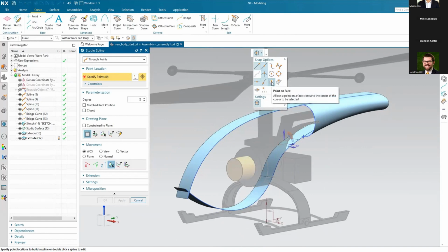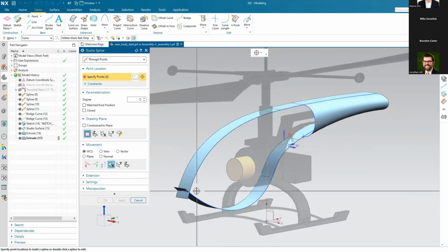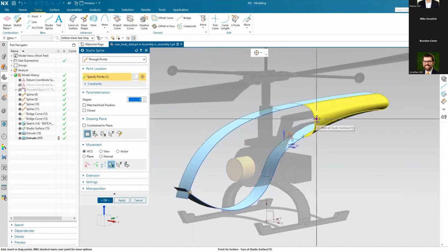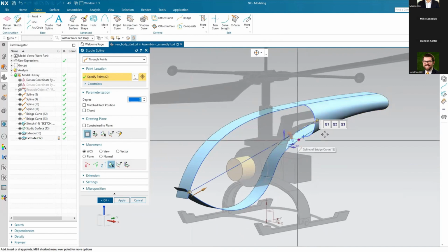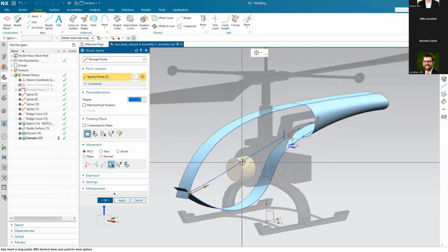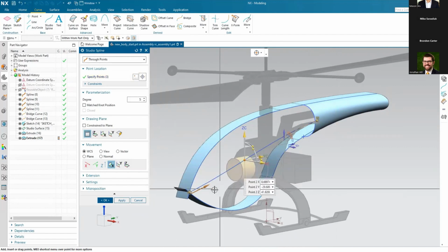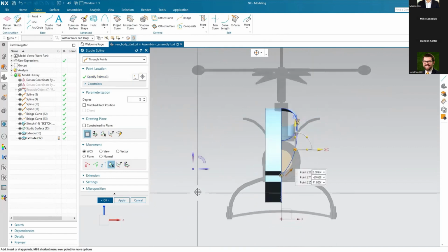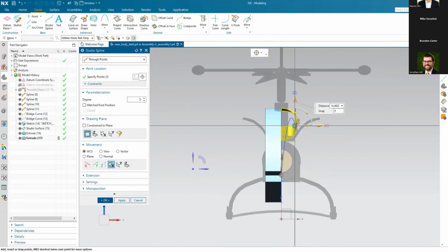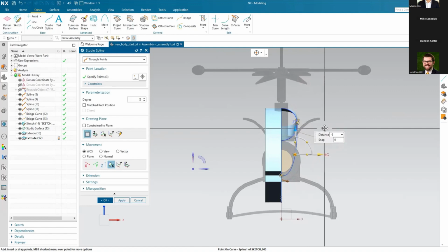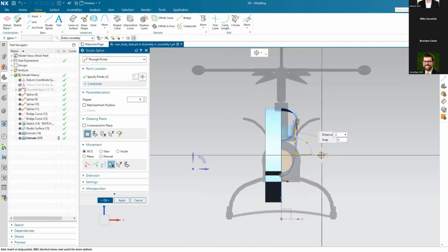With this, you have our snap options as you're creating. Here we have just a point location. In the back, we're selecting on the surface that we can use. Any of those help us in building, in this case, a 3D spline. What's nice too, with the selection and the snap, is you can put multiple locations across the spline and then use the drag handles to adjust those. If you want to do it just by moving the drag handle, you can, or you can put hard values into that at the same time.